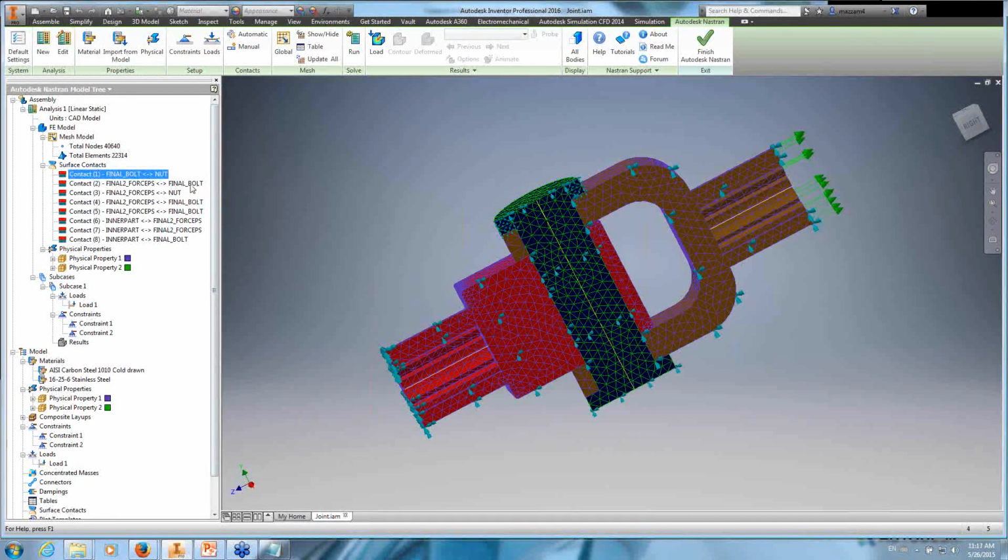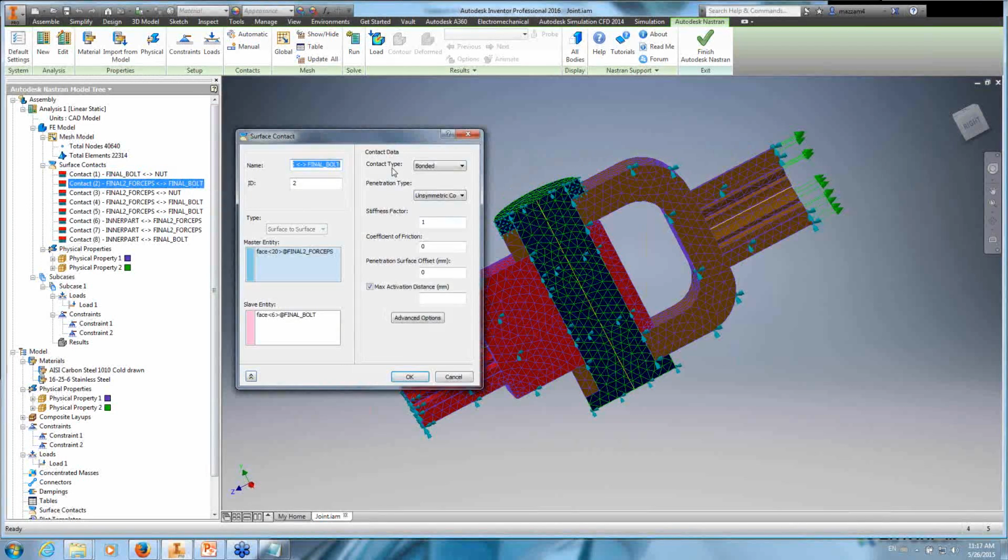So I'm going to go through these remaining contact pairs real quick. Let me show you first what the possible contact types are that you can set. And by the way, this little bubble that pops up here that says Nastran welded, this is the older naming. So we used to call that welded. Now we're calling it bonded. And if I click here and expand it, separation is basically the fully general contact. Parts can slide against each other, they can separate, and of course if they're pressed against each other, they're going to resist that penetration and establish contact. So separation is the general contact.